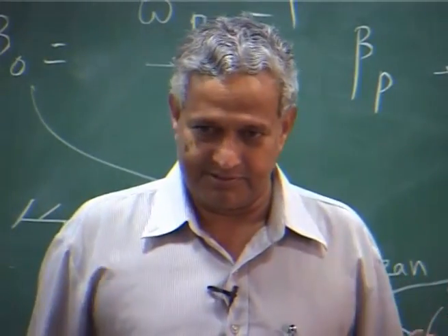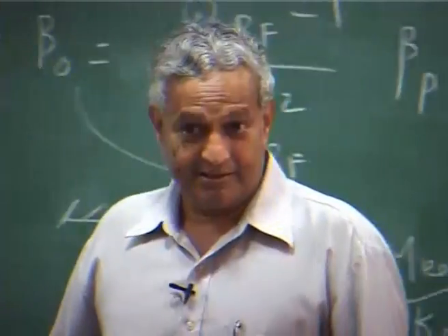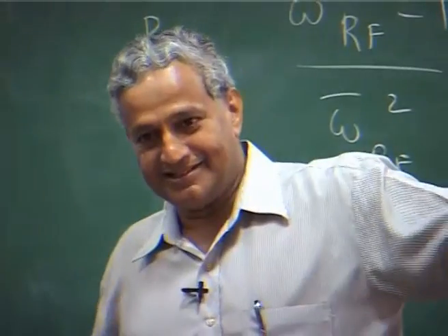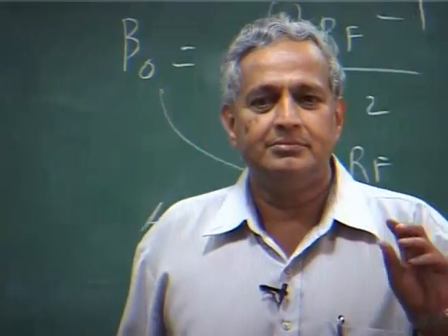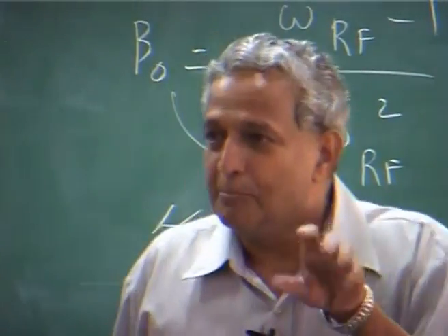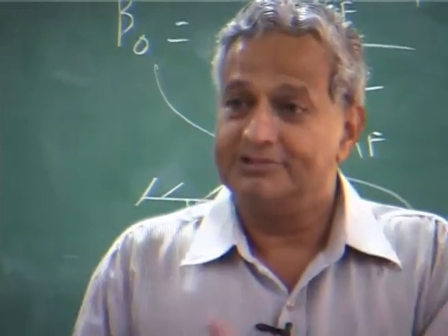okay, because then the design, that is why all are very important, but it has an effect on damping also, that part we will come later in the stability and other aspects. Right now the precone is given to relieve hub mean moment slightly, otherwise you have to design a bigger hub.